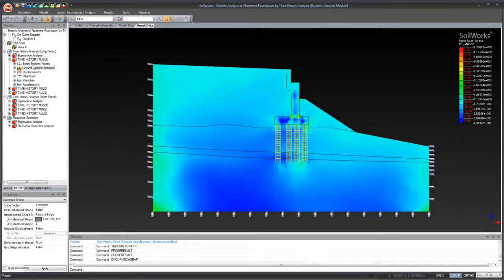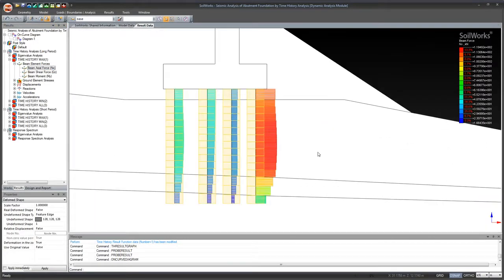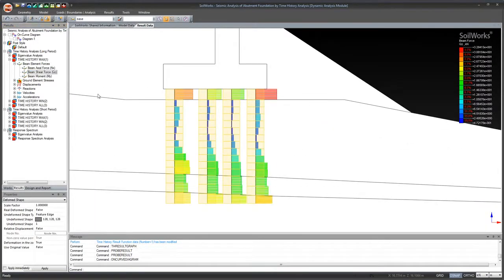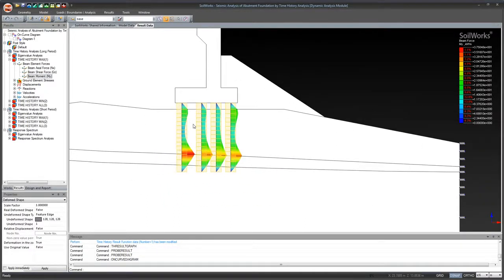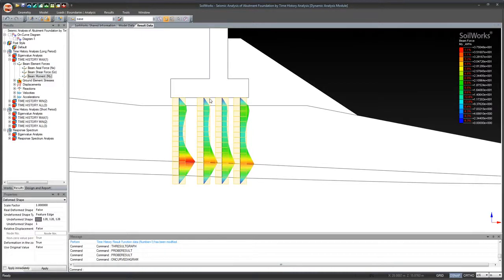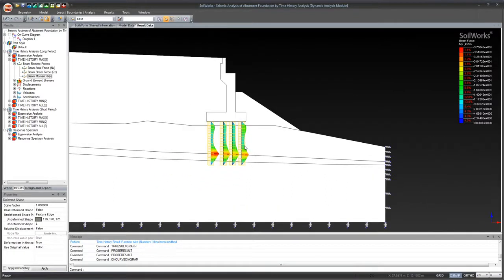In order to view that, just go to Beam Element Forces. So click on this tab here, and let me zoom in here for you, you'll be able to get your axial forces, your shear forces, as well as your moments for each of your piles. So something also that is very useful. Typically engineers will take a screenshot of this, and they'll have maybe some sort of spreadsheet with the maximum and the minimum values. They'll have that in their final report. And just keep in mind that all of these results are available to you for each of your analysis cases. So within each of these cases, you have two main cases, but then within that, you have a total of 3. You have your maximum, your minimum, and your all.